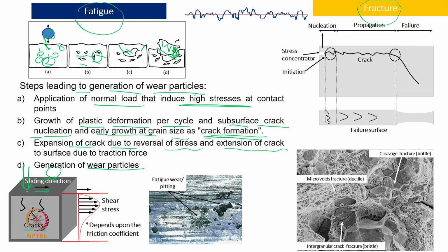What will happen is, because of the compressive stress and because of the tangential load, there will be shear stress, and we know very well that if the coefficient of friction is negligible, then the maximum shear stress will be subsurface, below the surface. However, if the coefficient of friction increases and there is more and more resistance in the sliding direction, then the maximum value of the shear stress will reach the surface. When it happens, quite possibly the wear debris particle will come out,